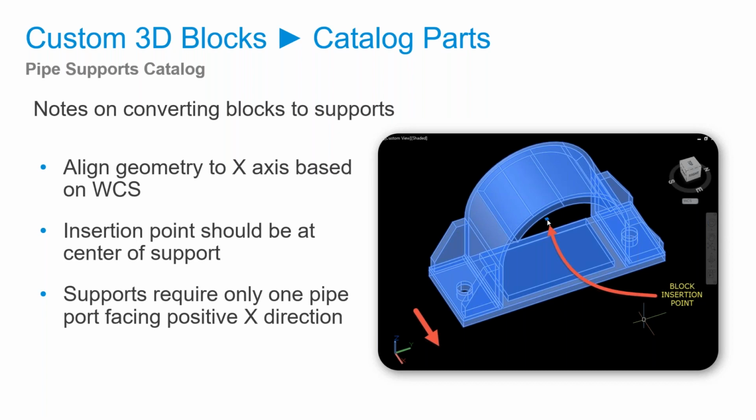And you also need to create the port. So that's what you do with the plant part convert command. You need to create this port in the pipe, at the center where the center of the pipe will be, and then again in X direction you will define the direction of this port with the plant part convert.